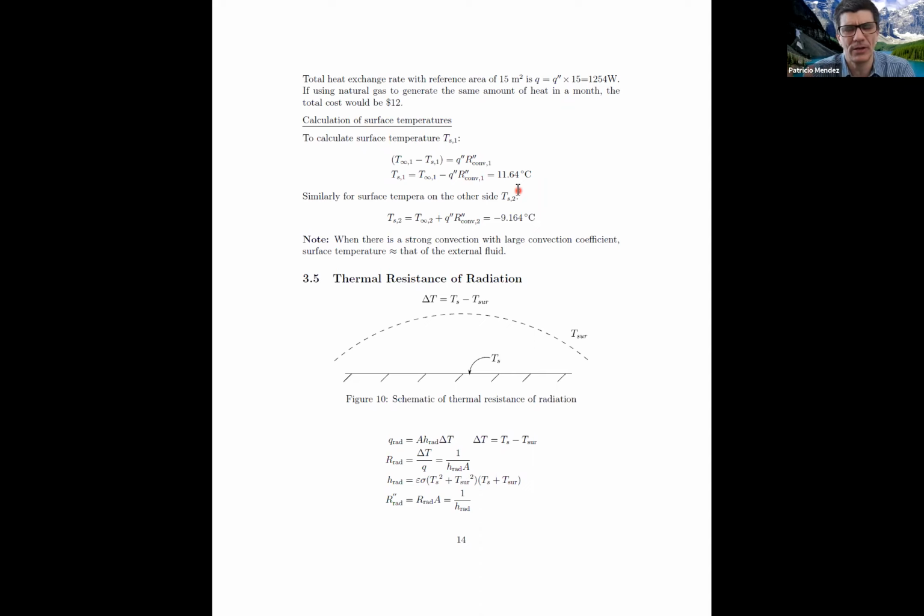We have the power to calculate this. Another interesting tidbit. So let's calculate our heat loss by radiation. By convection, I would do my heat loss of me standing here at my 37 degrees or 33 degrees, whatever the temperature of the surface of my skin, against the 20 degrees of the air in my room.